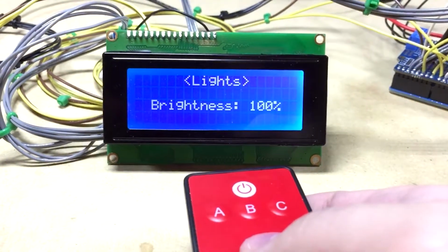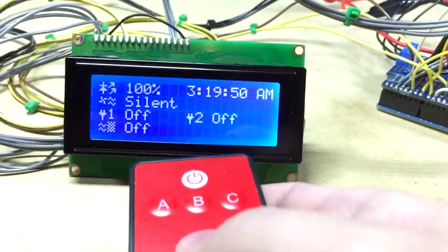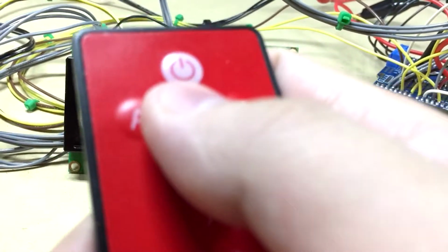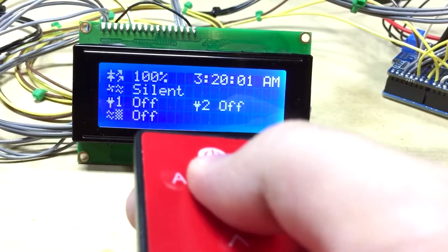That is the only reason the algorithm is even somewhat complicated, is because of how I did the lights. But it faded better whenever I did the fading on and off versus all of them fading together from off to on. And plus, when I hit 25% multiples, none of the lights are being PWM'd because they're all either on or off, so there's no noise. Whenever I'm using my oscilloscope and taking really precise measurements, I don't have to worry about noise being injected from PWM from just merely an inch below it. So that's why that took so much code, and now it's reworked. It does not take up much code. I figured out a simpler way to do it.